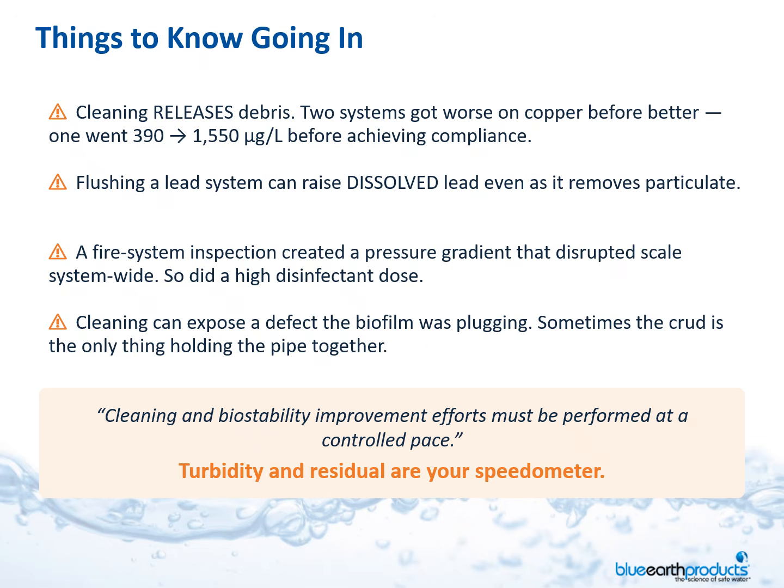And if you do have pinhole leaks, it's very likely that the crud that you're trying to get out of the pipe is what's actually plugging those holes. So you may see some pinhole leaks result just from your treatment. But these are temporary situations, and they need to be managed and controlled to get through it. It is possible to use turbidity, and the chlorine residual is kind of your speedometer, using a residual to see the progress you're making, but turbidity to make sure that you're not doing it too quickly.